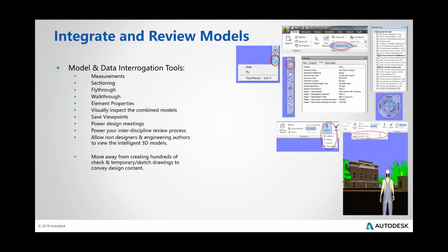So there's also the avatar there that you can see. It really allows you to get a little bit of perspective and scale as you're walking around and navigating through the models. Viewpoints as well can be saved out. Now, again, these may not seem critical, but they kind of are. Setting up a whole lot of saved viewpoints really helps others coming into the model navigate through and find those areas of focus that you may want people to be looking at.